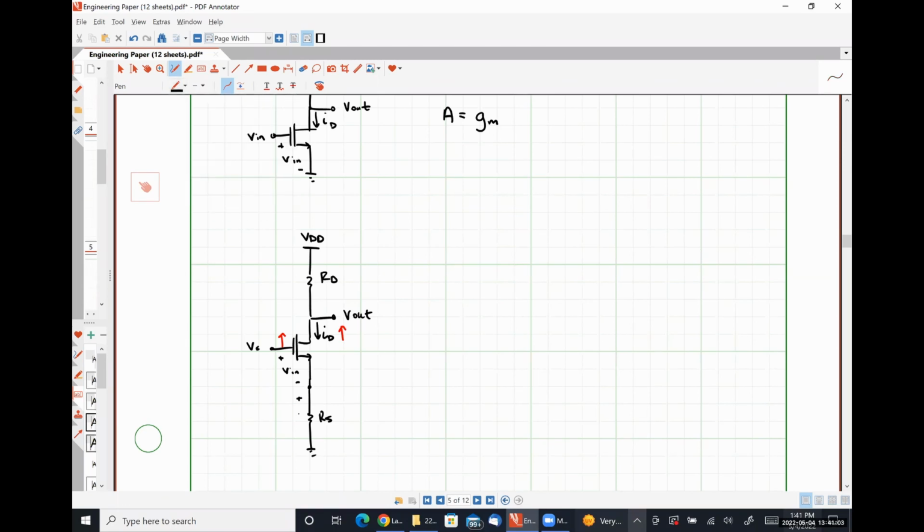So if we had a voltage here, VRS, when our source voltage goes up, our drain current goes up, which in turn causes VRS to go up. Well, VRS going up causes VGS to be smaller. That opposite thing, qualitatively following our signal path, is what tells us that we have a negative feedback system, or at least it's behaving like it has negative feedback.